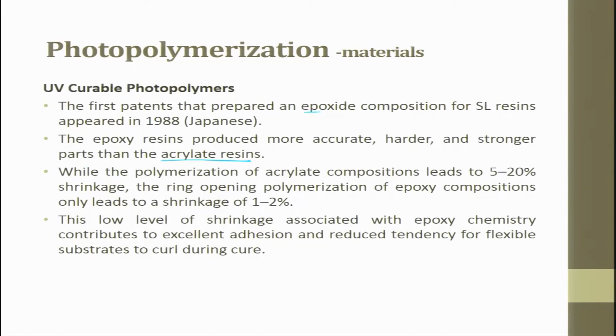While the polymerization of acrylate composition leads to 5 to 20% shrinkage, the ring opening polymerization of epoxy composition only led to a shrinkage of 1 to 2%. Then people started getting away from acrylate based photopolymerization to epoxy composition photopolymerization.